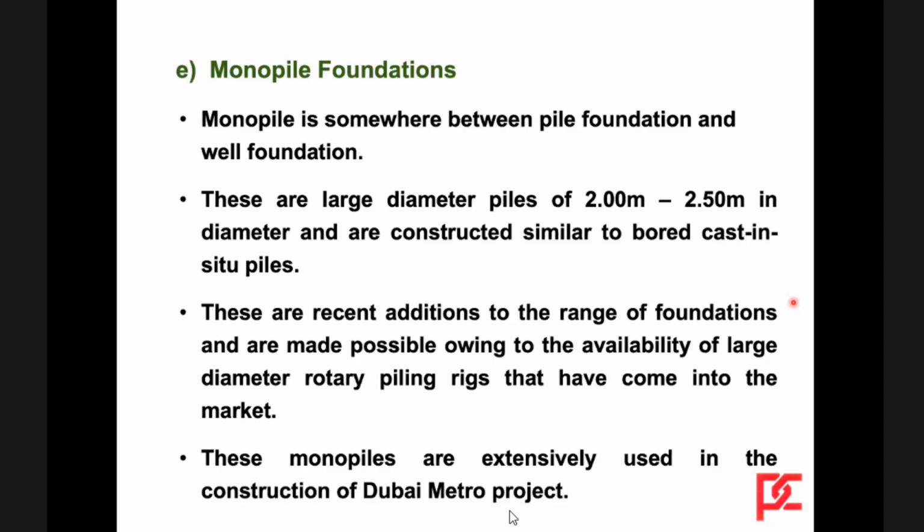Monopile foundation is somewhere between pile foundation and well foundation. These are large diameter piles of 2 meters to 2.5 meters in diameter and are constructed similar to bored cast in situ piles. These are recent additions to the range of foundations and are made possible owing to the availability of large diameter rotary piling rigs that have come into the market. These monopiles are extensively used in the construction of the Dubai Metro project.